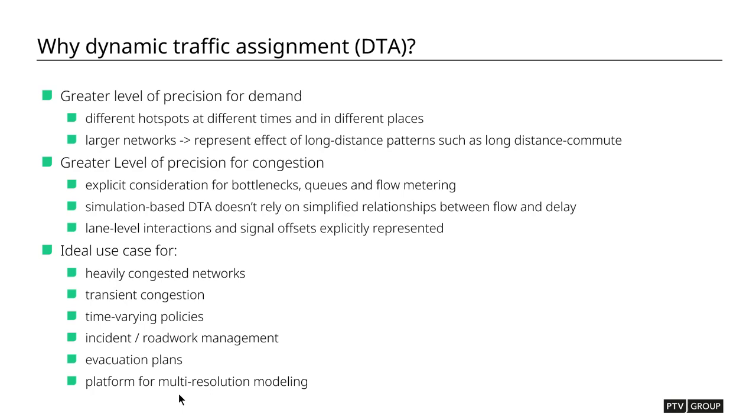You can also model time-varying policies, so that applies generally to temporary changes that could be referring to speed, to tolls, but you can also model something like road and lane closures. Incident and roadwork management are applications as well as evacuation plans. And as mentioned before, dynamic assignments are useful to get more realistic inputs for microsimulation and therefore are useful for multi-resolution modeling between different levels.